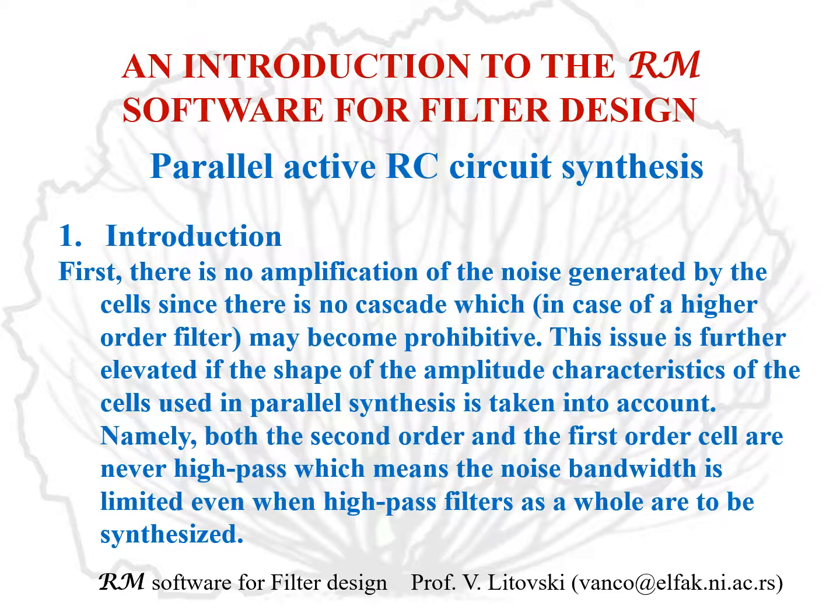This issue is further alleviated if the shape of the amplitude characteristics of the cells used in parallel synthesis is taken into account. Namely, both the second order and the first order cell are never high pass, which means the noise bandwidth is limited even when high pass filters as a whole are to be synthesized.